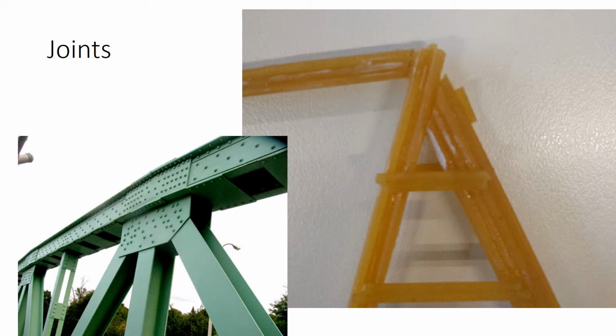The use of gusset plates on the joints of a truss helped to join members and support each joint. During construction, when joining the members, we were concerned the joints would be weak due to uneven joins from cutting. Using individual strands of spaghetti across the joins, we were able to simulate a gusset plate on our bridge. These strands are zero-force members, but when the bridge begins to deform under load, they help to prevent buckling of compression members and also carry some loads.